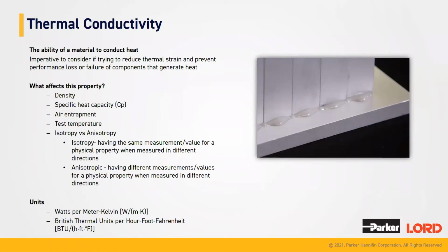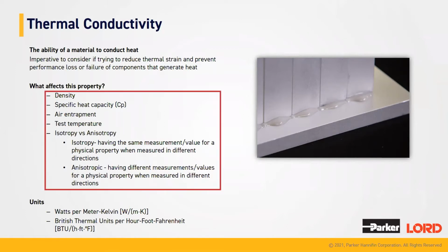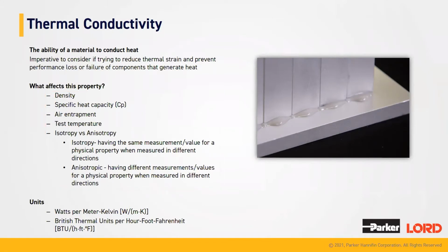Now, what affects that property? So the type of filler that is used when formulating the product greatly impacts the thermal conductivity. So that relates to the density, the specific heat capacity. Any air that is entrapped in the material when it is applied will impact the thermal conductivity, as well as the temperature of the application or of the test.